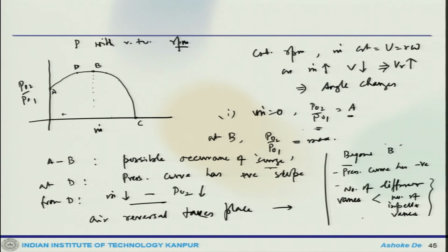Now, since each is supplied by several impellers, this can be evened out. Now, even in this case, at low mass flow rate, all the diffuser passages will go into surge simultaneously, adding a limitation between B to C. So, there is still a possibility. So, one has to be careful.